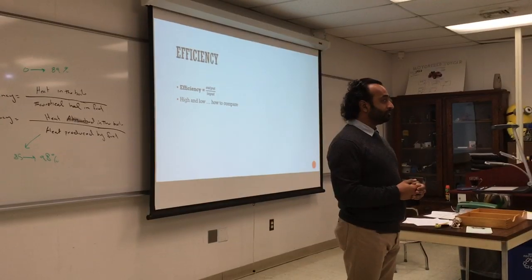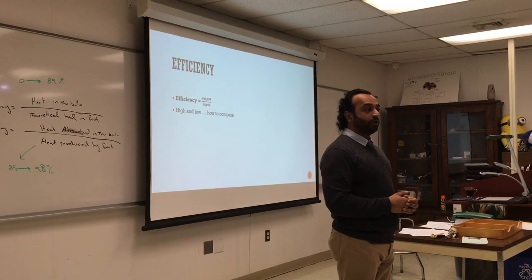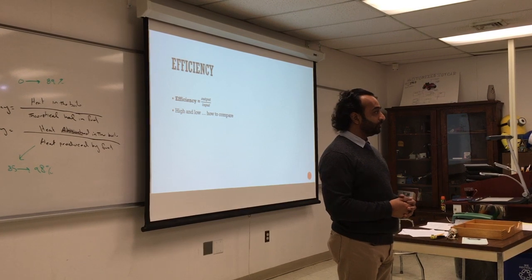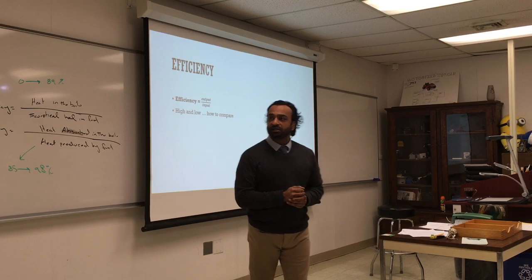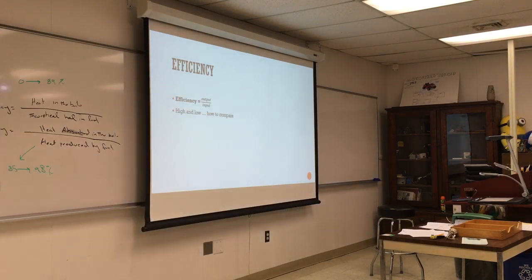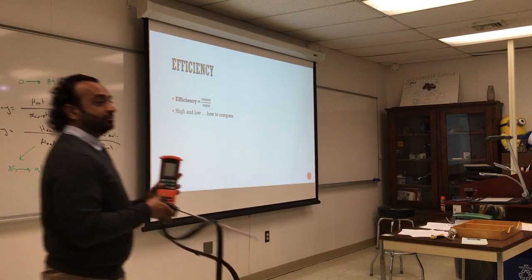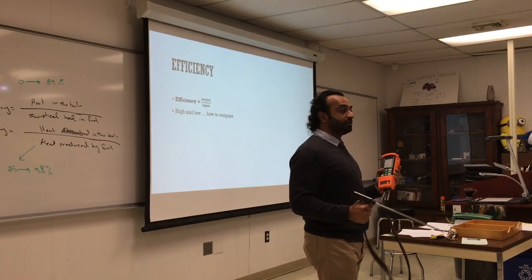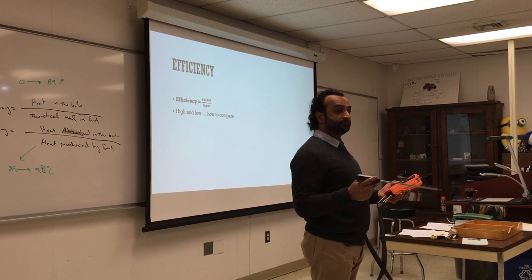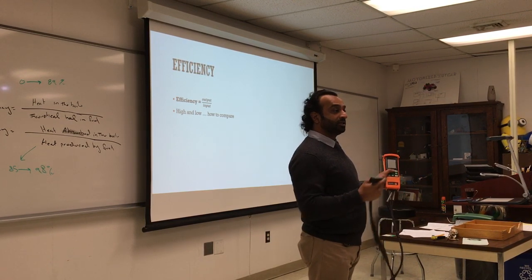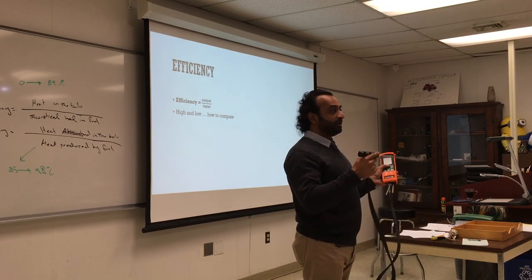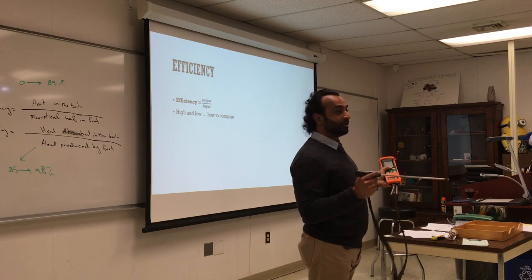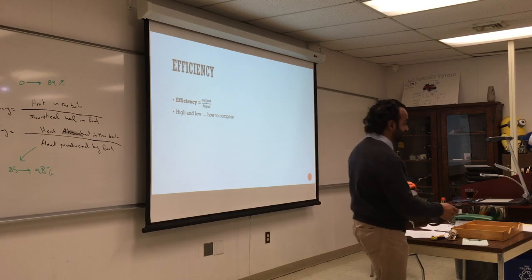That's when you get the actual combustion efficiency. In the beginning, the boiler is cool, it's not going to burn very well. When it gets hot, it will stabilize and give you the right efficiency. Actually, with some of the new combustion testers, like this one, you can keep that on and stick it into the vent, the flue pipe, and you will see the combustion comes up until it's stabilized. So you put it from the beginning, it will start at 50, and it goes up to like 87, 89, and it stops in there. So 87, 89 is pretty good.